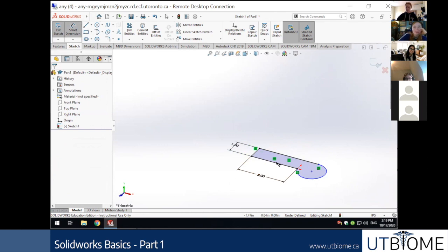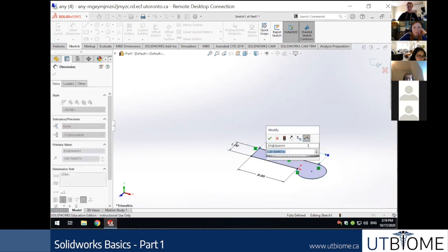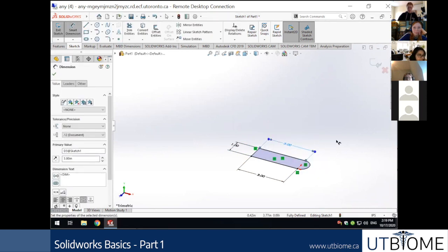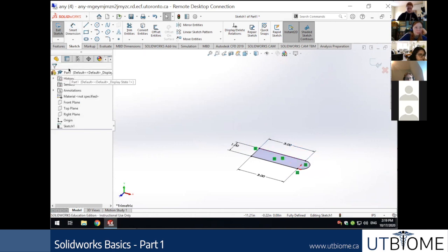Okay, so this is where you're at, right? You probably want to face this dead on, don't you? Yeah, for sure. I can at least get you to do that for now. So hit the check mark at the top left. Okay, so you're going to go down to sketch. It's straight down from where you are right now. It says sketch 1. Right click on that. And then not that one. Yes, the icon that is a blue rectangle. Left click that.